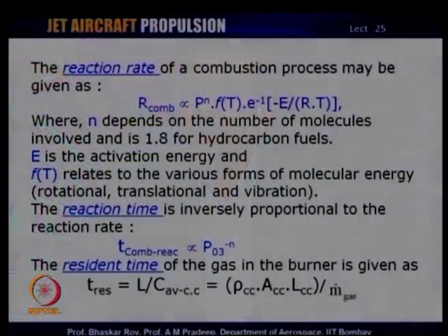Now, let us look at the other parameter that is very important for the combustion process, and this is the reaction rate, which is given in terms of a number of parameters. Now, pressure to the power n depends on the number of molecules involved in the process of combustion, and it is normally 1.8 for hydrocarbon fuels, which are normally used in aircraft combustion.